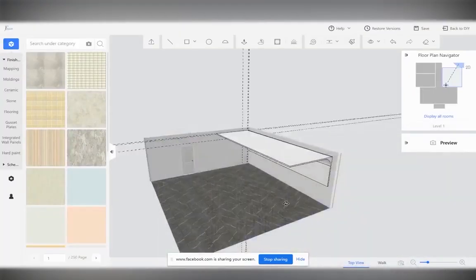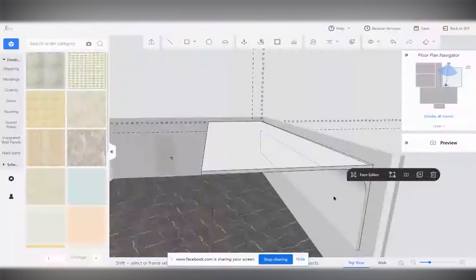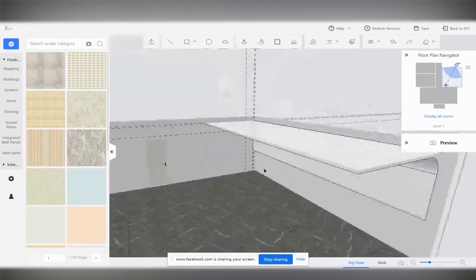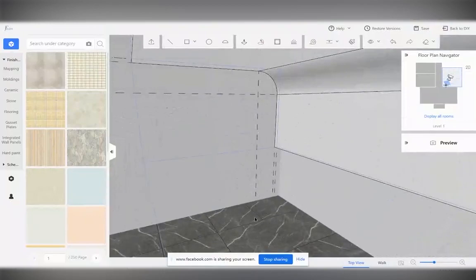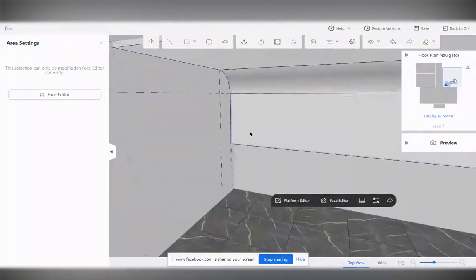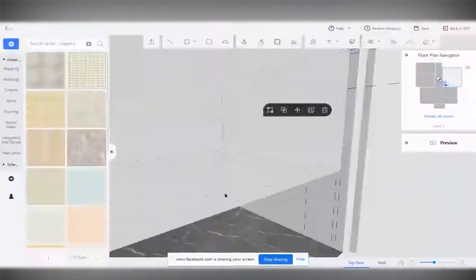So we drag it out, select one face, and hold Shift and double click on the selected face here. Then we select the entire group. So we group it to make it much easier to move or to duplicate. Shift and double click will let you easily select the entire adjacent surfaces as a group. I think this is super useful.